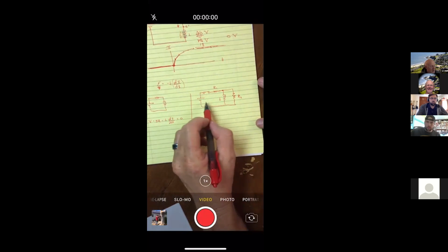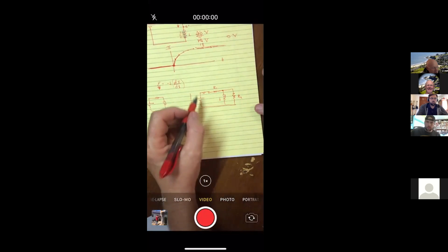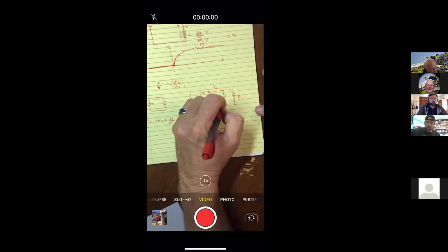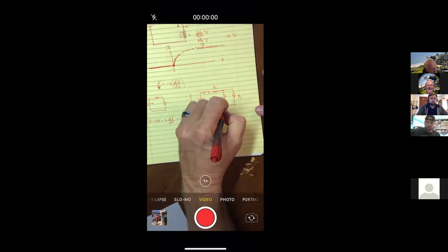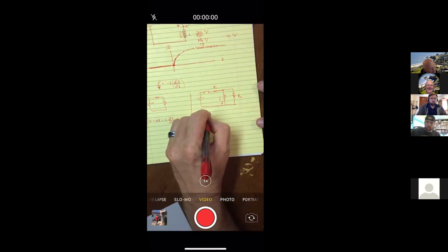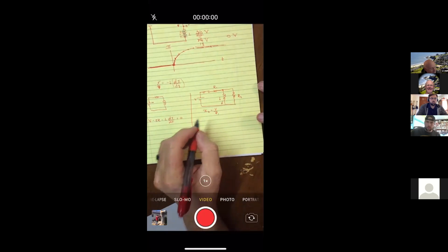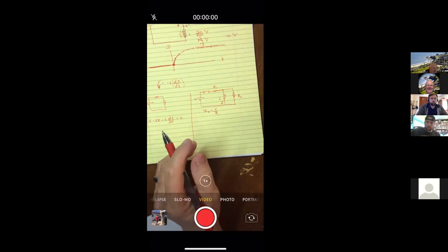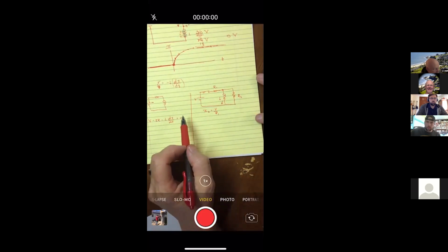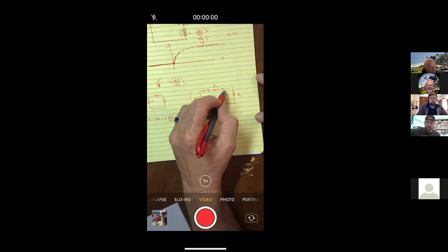And if you left the switch closed for a long time, eventually all the current would be going through this inductor. So the current would have an I, I'll call it I naught, because it would be this V divided by R1. So that when you de-energized it, that is when you open the switch, the current would continue to go around this loop.